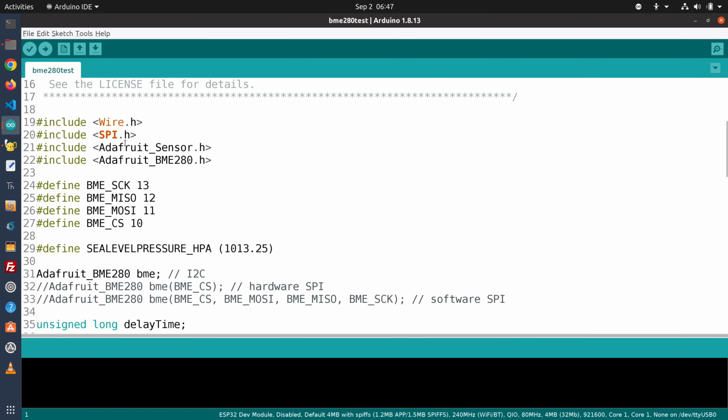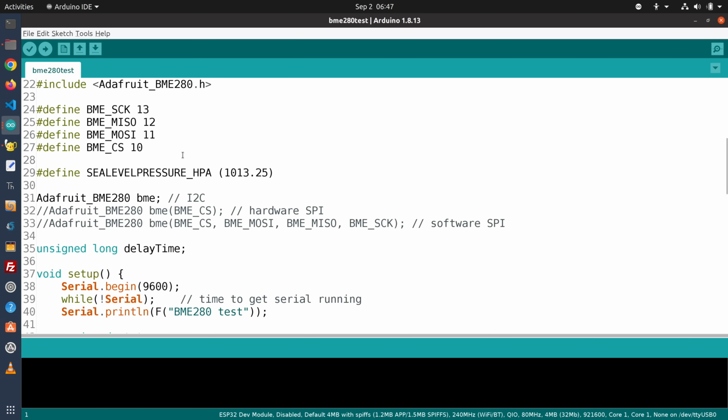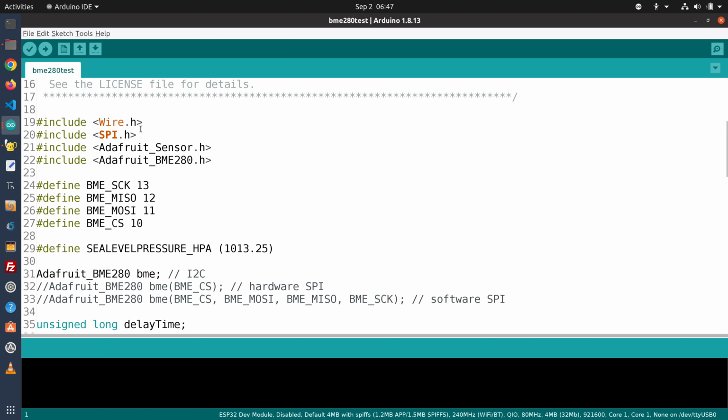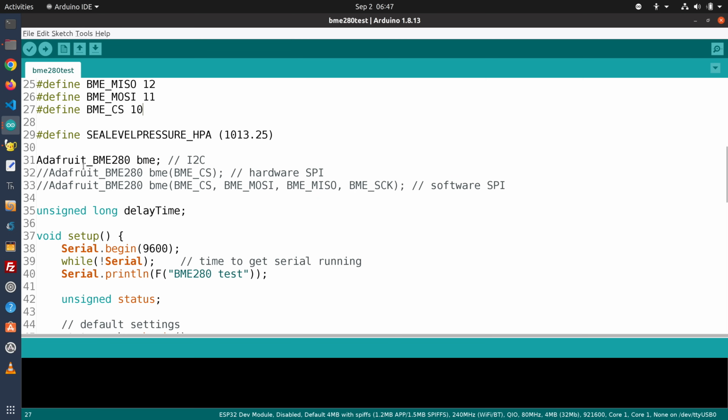It basically just shows you how you can use the BME280 library. It shows you both the connections for the SPI and the I2C, which is why it's including the SPI bus and why it has SPI connections. But over here, they've not remarked out the I2C, and they've remarked out everything for the SPI. So if you want to use the SPI connections on this, you can modify it as well.